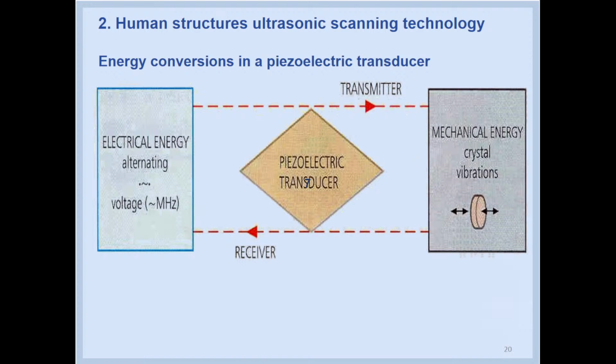This is the direct piezoelectric effect. This effect is reversible. That is, if electrodes are placed on the crystal plate and a potential difference is applied to the electrodes, the plate will be deformed by the electric field. This is the inverse piezoelectric effect. In an alternating electric field, the thickness of the crystalline plate follows the variation of the electric field.